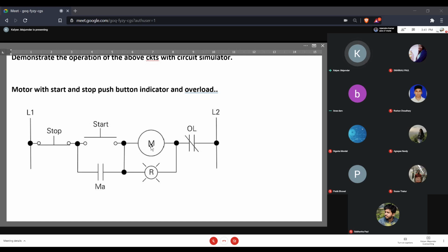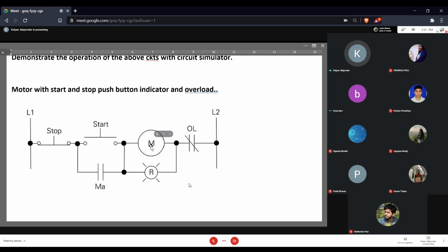Okay, for example, say in your home, you could see that you have two types of switches. One is normally rated for 6 amperes, the kind of switches that you use for your lamps, for your fans, and all other devices. But you'll find that for your geyser, for your refrigerator, you have a bigger switch because that has a much higher current rating, typically 16 amperes. So higher the current rating, you have a bigger set of contacts which can withstand that higher level of current.